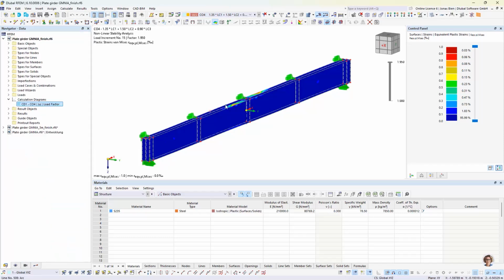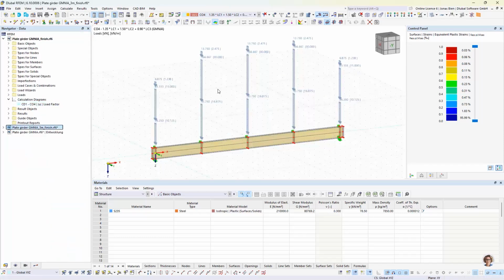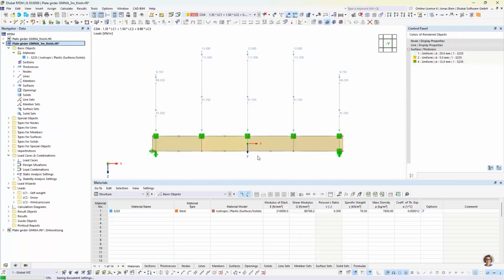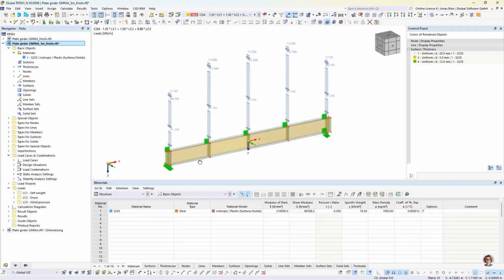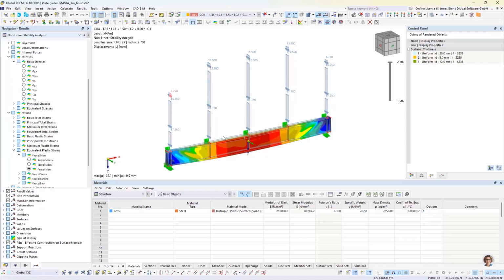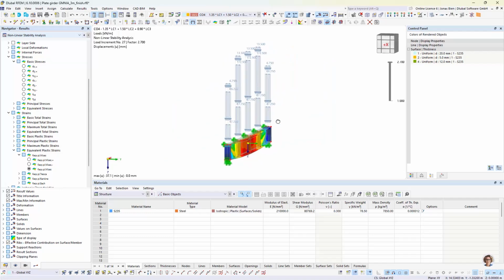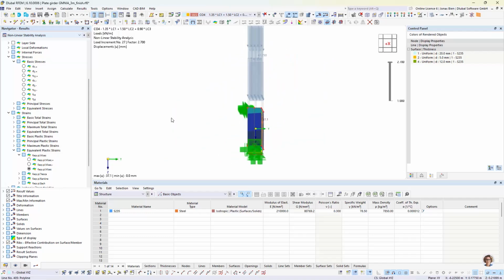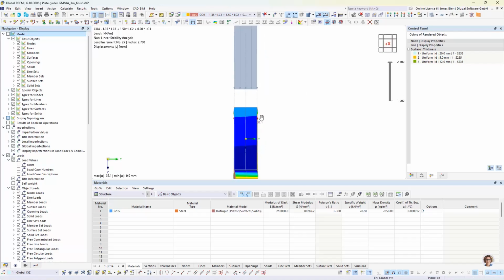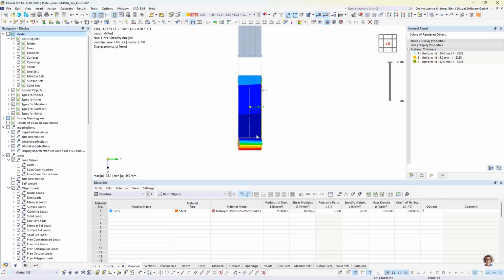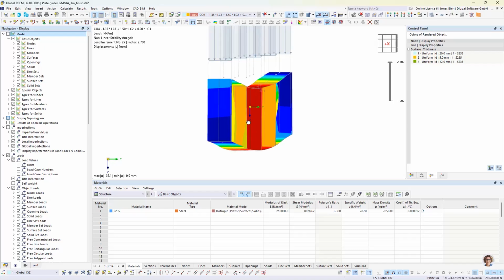And it's in the next step also interesting to see what happens when we change certain parameters. For example, I simulated the same girder with the same loading conditions, just with shorter buckling panels of 3 meter. And when assessing the results here, it looked quite different. Of course, due to our imperfection, we also have some transverse deformation occurring in the model, but they are not as pronounced as before.